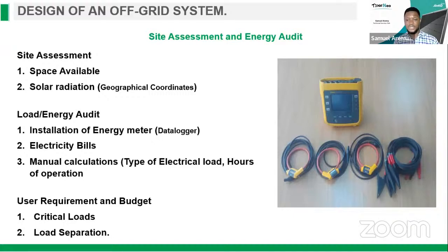And from this, you can actually analyze your data to know what is the peak load, what is the average load, what is the total energy consumed from probably 8 in the morning to 4 p.m. in the afternoon, or the energy consumed at night. So from these results, you're able to efficiently size your system. Two is that you can also understand the load consumption pattern with the electric bill. On the electric bill, you'll see the total energy consumed in a month, per week, and from that, you can know the energy consumed per day or per hour.